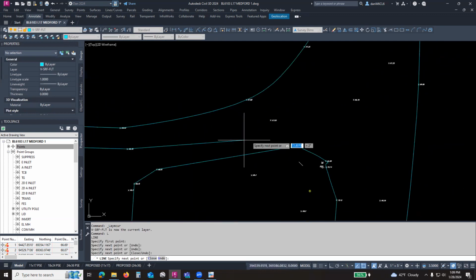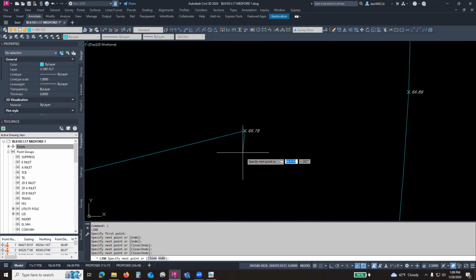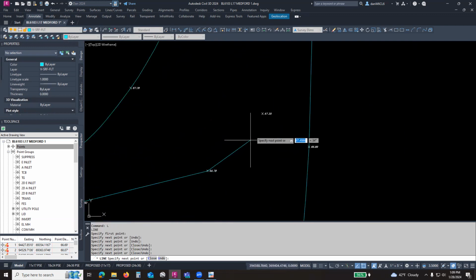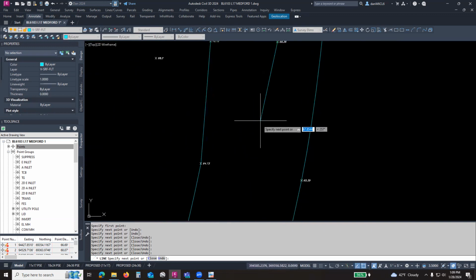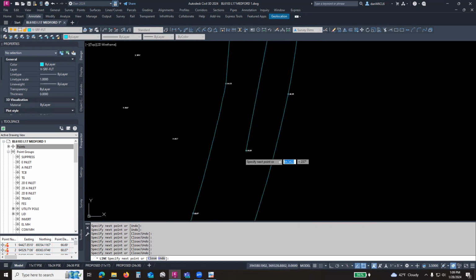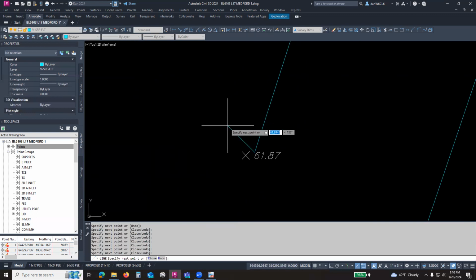because as you know, the center line of the road is generally higher than the edges to prevent ponding in the middle of the road. Oops.